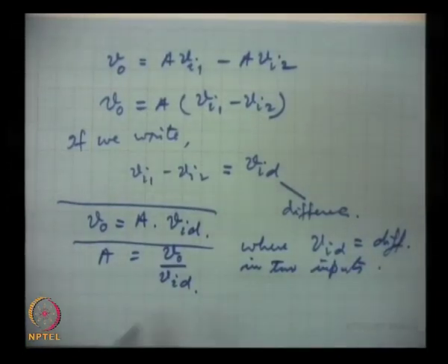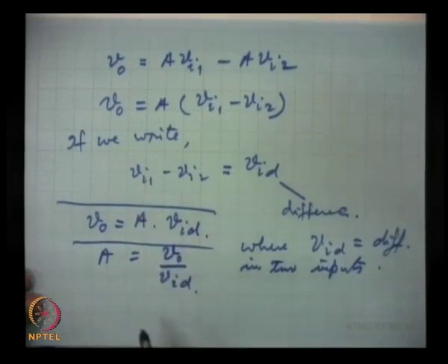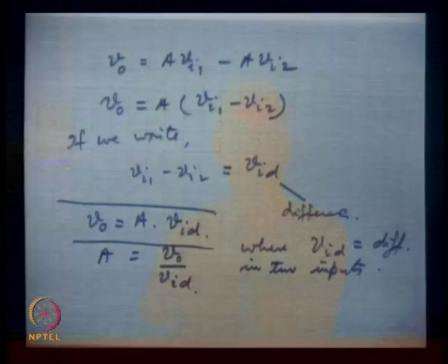So this is a very important analysis, and it has brought out several important features of the differential amplifier: that it acts as a differential amplifier, plus the two inputs, one is the inverting and the other is the non-inverting input. Then we take another parameter from this AC analysis, and that is input impedance. For every amplifier, input impedance is a very important parameter.